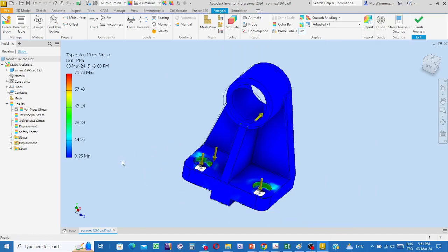But without referring to the material library, physical or digital, to be able to directly see whether there is a risk, ask Inventor to show factor of safety. Bring the cursor onto the factor of safety option, right click the mouse and say activate. If you select the activate option, then Inventor will indicate the factor of safety. I see the factor of safety of the body is in the order of 50. It's quite safe. The smallest factor of safety is in the order of 3,